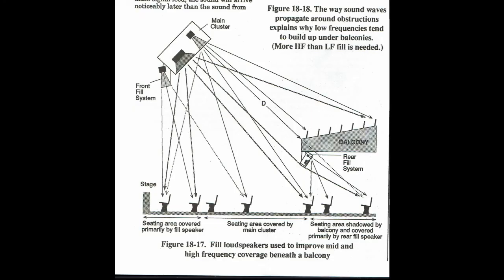So now we move into the loudspeaker hookup methods. This needs to begin with another caveat. If you don't know what you're doing, don't do it. It is very easy to damage either the power amplifier or the loudspeakers if speakers are hooked up incorrectly. It's always important to understand what the manufacturer's recommended practices are before connecting any type of speaker to the power amps, and definitely before turning anything on.